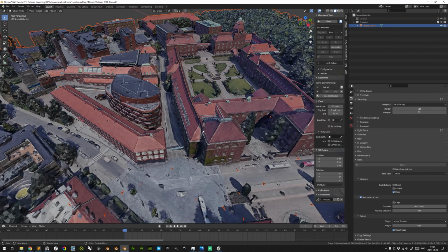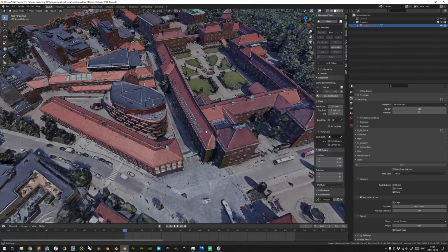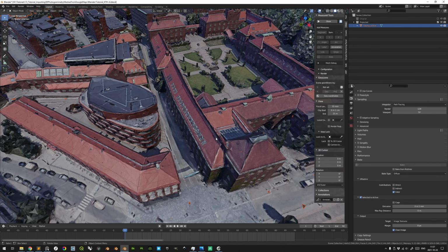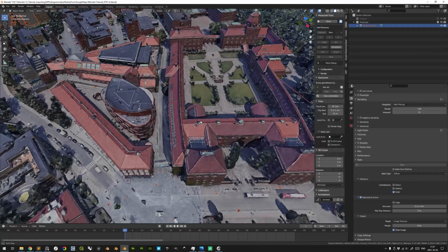Because the UV space is constricted, as long as you only use one texture, you are constricted to the UV 0 to 1 space. And the more mesh faces you try to fit in one UV 0 to 1 space, the smaller the portion of the total area those faces have to occupy to be able to fit everything in one texture.